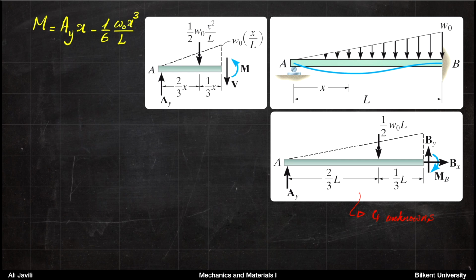In order to do that, we proceed exactly as we spoke about. So we will write our equilibrium equations, obviously, but we should also use our elastic curve as the additional equation helping us to solve the problem. So if you start from the left-hand side, here you have Ay, which obviously we don't know what it is.